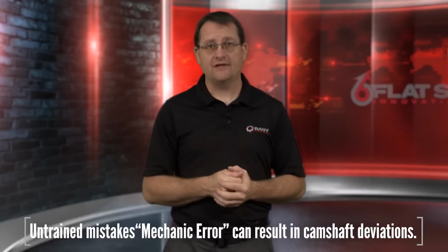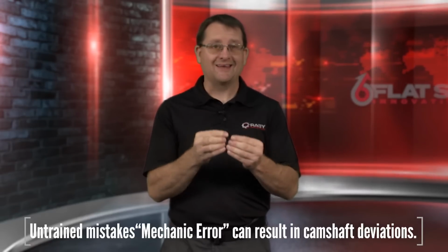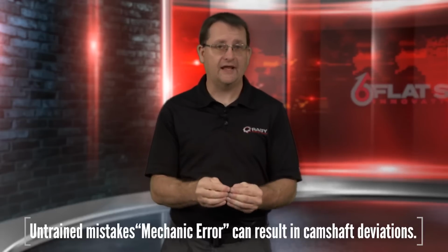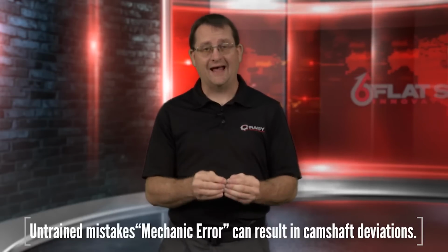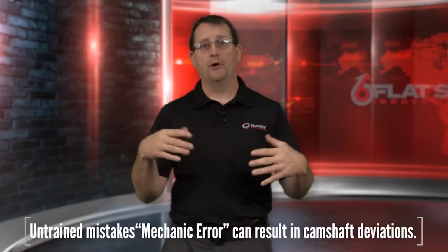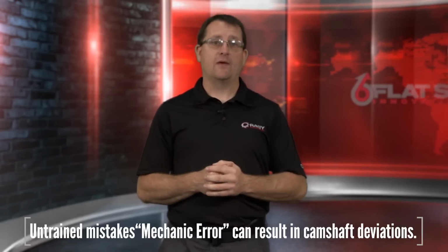You can have camshaft deviation problems that are created by an incompetent person who is not well understanding of the way these engines are timed, the way these engines are built, or what components wear within the engine. If you have that scenario, that particular technician or mechanic, if you will, ends up creating your problem for you, because he may not use the proper tools to set valve timing, he may not use the proper tensioners or the right jigs or have any of the things in place while he's doing a repair procedure or an engine rebuild. If that happens, it's pretty easy to correct his problem.